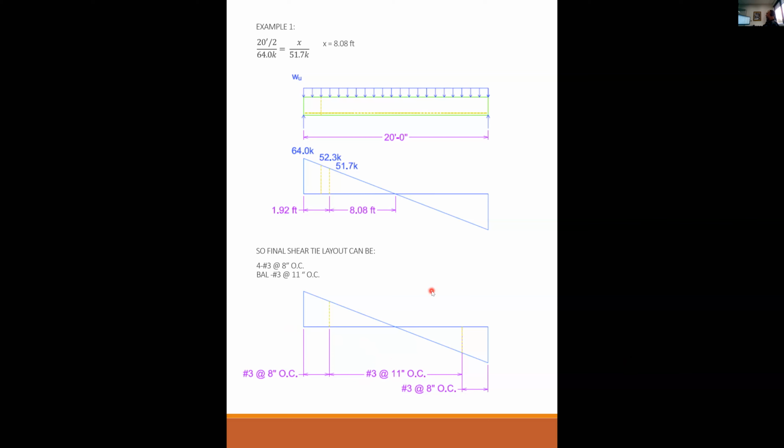But back to real life, the real life difference is much more profound. A very common beam reinforcing schedule that I will use is number 4s at 4 inches for 5 feet, then number 4s at 6 inches for 10 feet, and then maybe number 3s at 12 inches for the middle region. That's something I would use in the real world fairly commonly. Well, no, that's not with any given load. That's with loads that we deal with fairly commonly. We do a lot of parking garages, so the loads are pretty much the same over and over. But we do some interesting things.